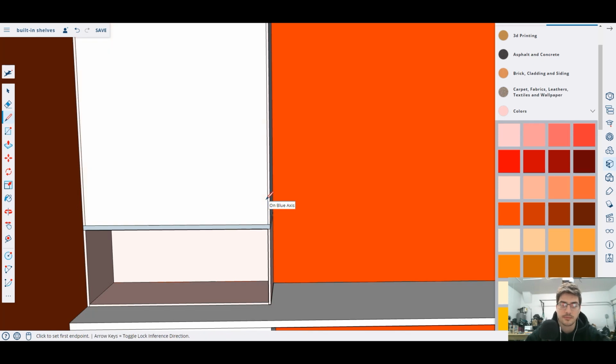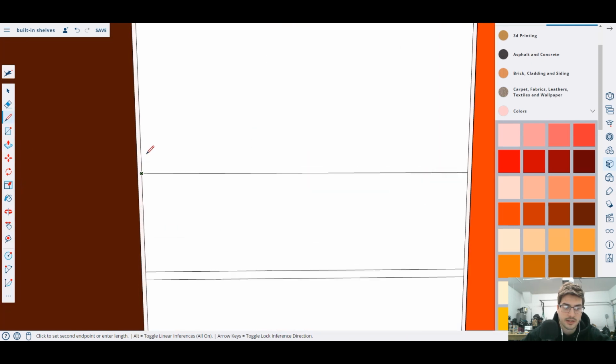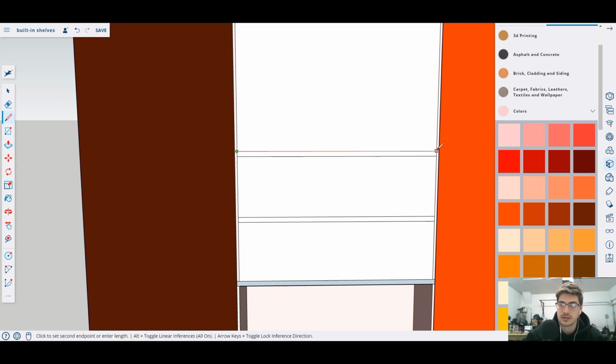Okay, the standard sizing for shelves from that point on, like you could do a couple big shelves, like you definitely could if you wanted to. But I'm going to do all 12-inch shelves, which is kind of like a standard bookshelf spacing from that point onward. And so I'm just going to do them all 12 inches of gap and then 1 inch of like actual thickness of wood, and then another 12-inch gap until we get close to the top so that you can quickly see how easy it is to model like the rest of these shelves.